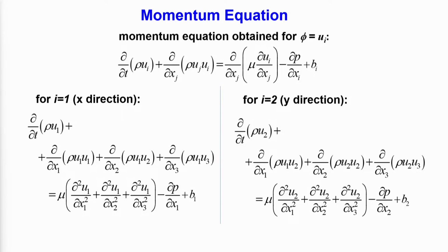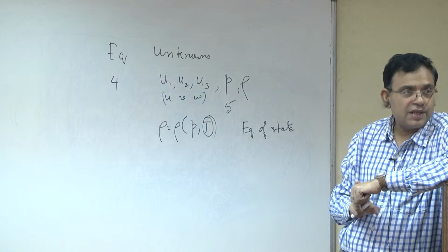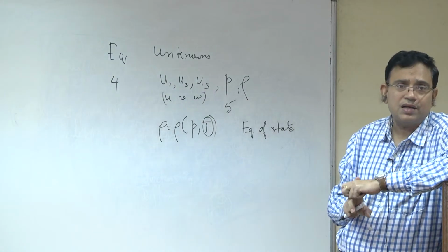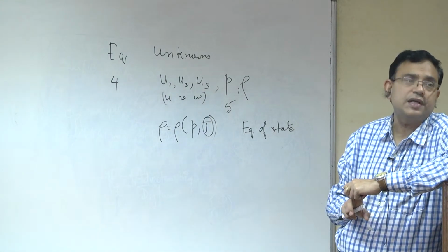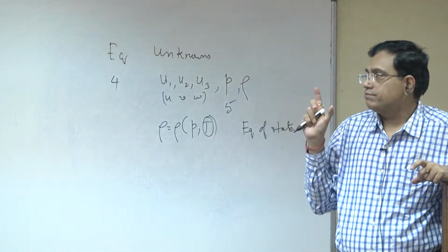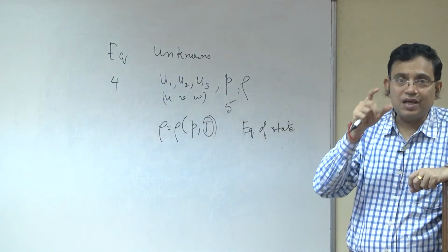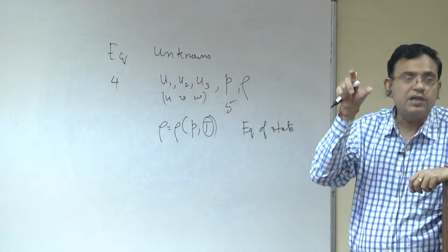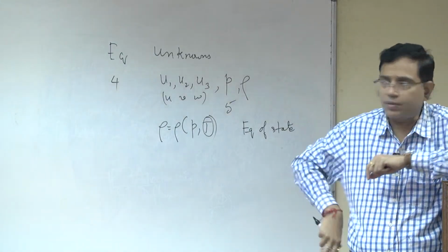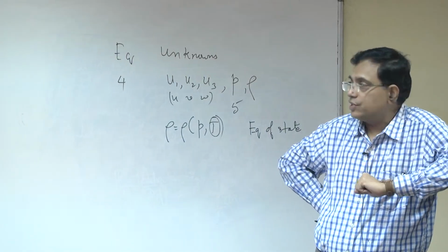So, dealing with non-linear equations is a challenge, because with linear equations you can use certain properties both for analytical and numerical solution, but non-linearity handling usually will always require an iterative method, and that iterative method has its sort of vulnerability to convergence. You cannot use something like the Lax equivalence theorem, and you have to do the grid independent study, all those things come up. So, non-linearity, coupled nature.